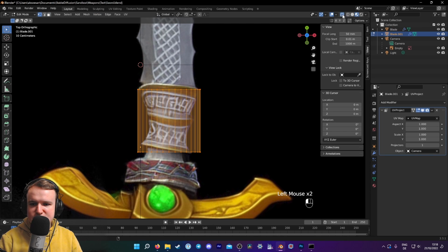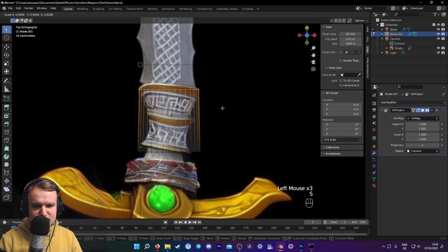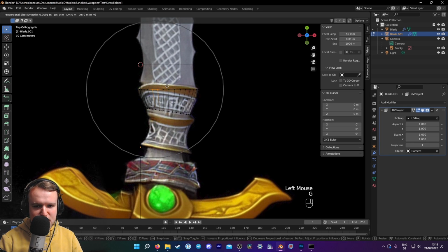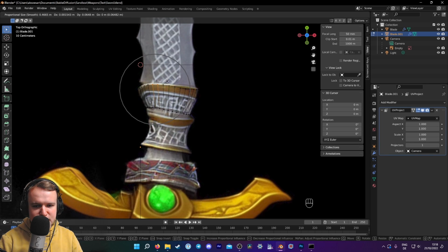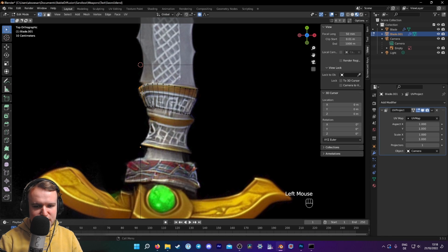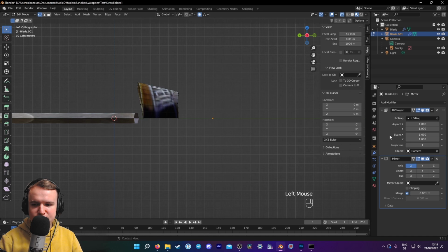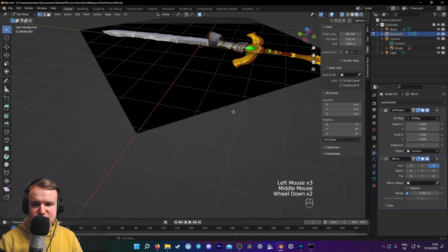This helps up here. It's the X-ray mode, or Alt-Z you can click to get in there, because then you can see all of the vertices you have going on. So I'm just going to adjust all of this. The material is already on it, which is really cool. You can go into proportional editing up here and scroll wheel, change the shape, and just move everything into place. And we can add a mirror modifier as well, right? So for that, you just delete these bottom vertices here and add a mirror modifier on the z-axis, and same difference basically.